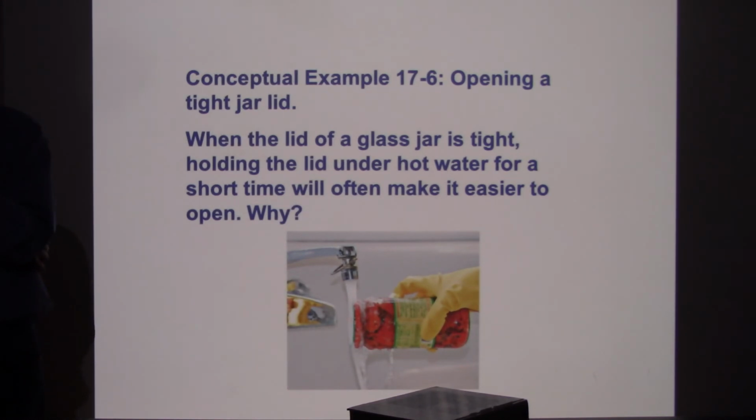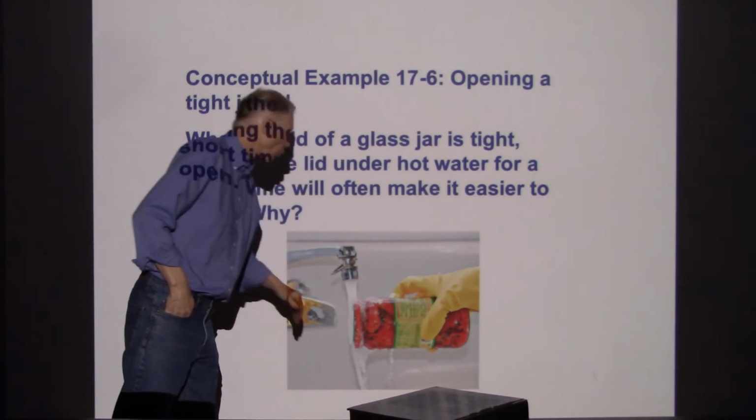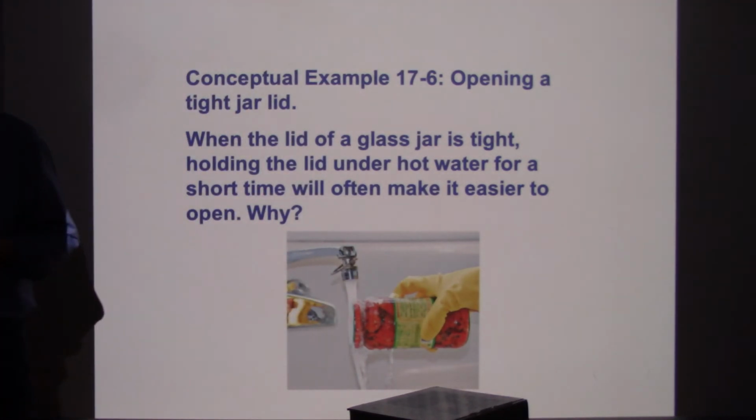So even if the glass heats up a bit, temperature goes up, we'll only get a little bit of thermal expansion. The metal will expand by a lot more, so as we go to higher temperatures, we can get the metal to expand, and that may solve the problem.